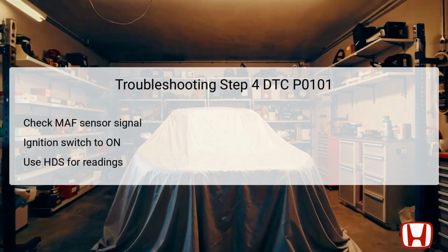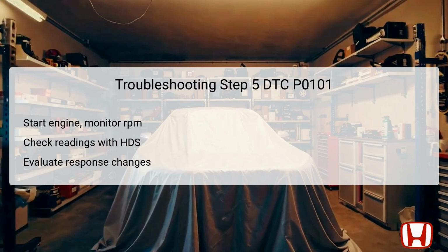If the readings do not fall within this range, it indicates a potential problem with the MAF or IAT sensors. Should the readings be acceptable, you can then transition to the next step to further diagnose the situation and ensure complete vehicle functionality. Step 5 focuses on checking the MAF sensor signal while the engine is running.